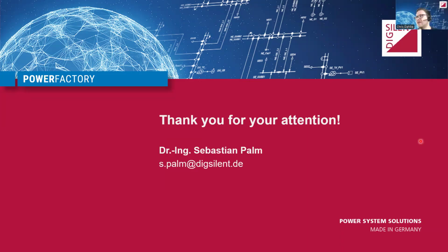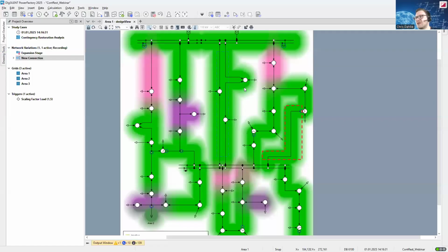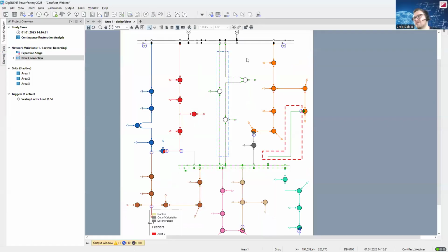Thanks, Sebastian. There were two questions now, or just one came in. I basically just left them open because I think they're good to discuss. Maybe we can go to the first question, which you might have covered briefly. So from Alan: in the N-1 contingency analysis, what level of switching actions for restoration of supply will be considered? Will it simply be resupplied from an adjacent feeder, or will the system shift load from the adjacent feeder to a third feeder to avoid overloading of the adjacent feeder when restoring supply after the original fault?